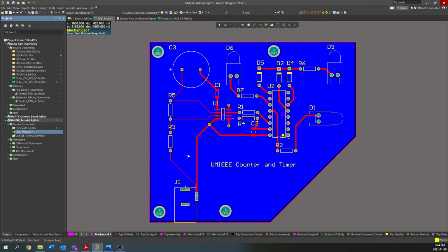Many of them, for example JLC PCB, have a visualizer on their site, so you can at least double check that you've uploaded the right thing, that everything is there, and you can see what the PCB would look like. You can set the solder mask color, the overlay color, and a number of other variables when you order your board, many of which are fairly self-explanatory once you've designed your PCB, other than, like I said, the copper weight, which is most normally 1 ounce. But other than that, I know I've gone a little over time here. I think that pretty much wraps it up.